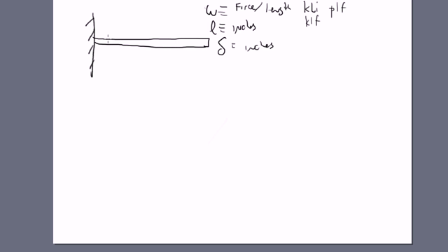And how one might go about designing something like this using mathematics to select the beam size so you limit the deflection to some number. So if we remember, we don't want to remember the individual details of all of these formulas. We do want to remember the two standards and some multipliers, and that is for a simply supported, uniformly loaded beam subject to a load of W at a span of L. We know that this will deflect.